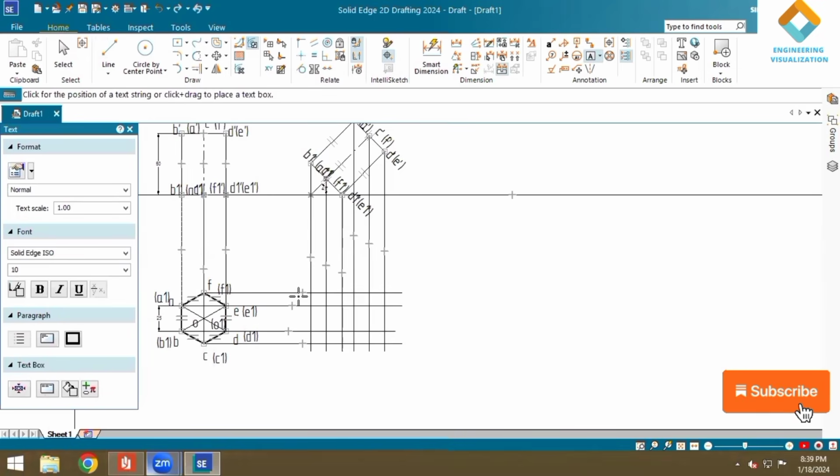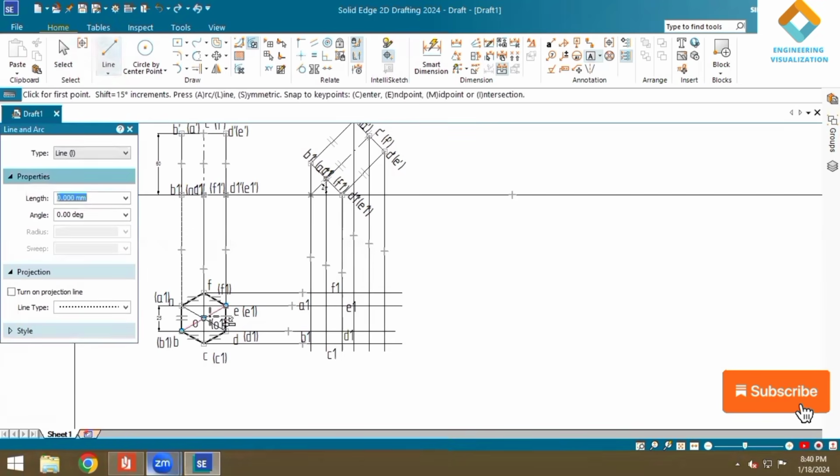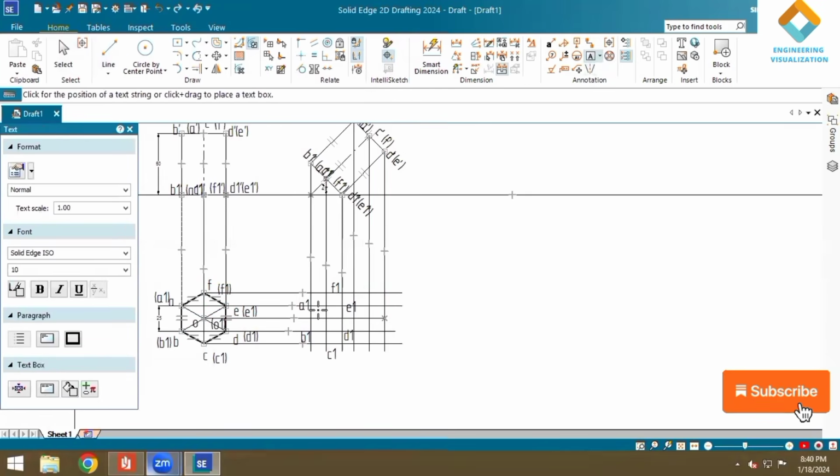So write the notation for the top view. In the top view, the bottom face is A1, B1, C1, like that you can write. Draw a projection line from O also. This is O1. In the same way for the top face, you can write A, B, C, D.